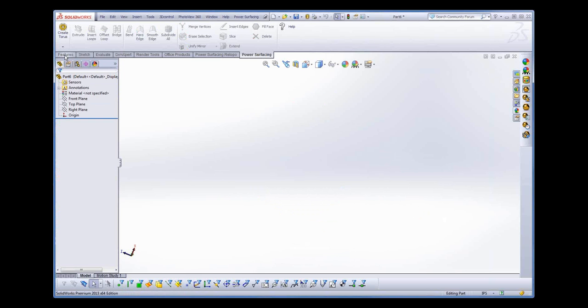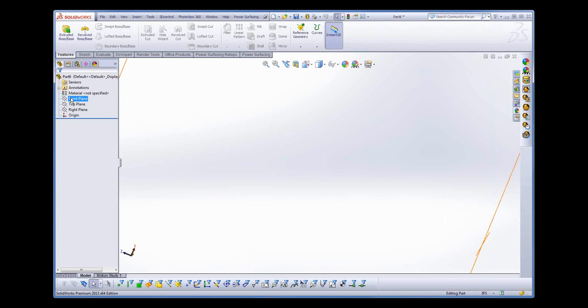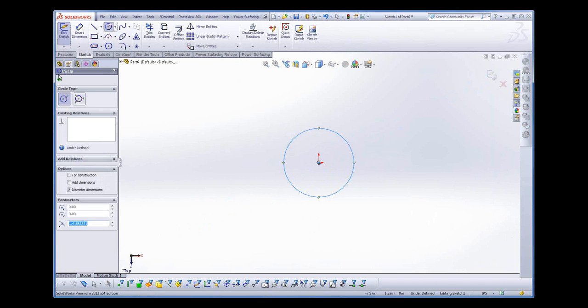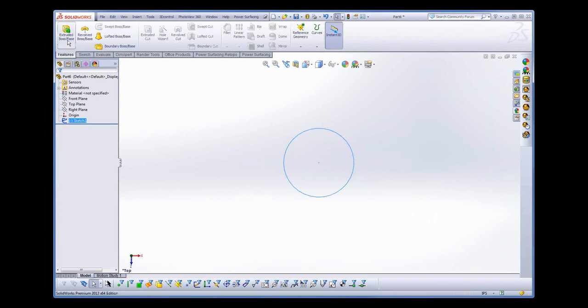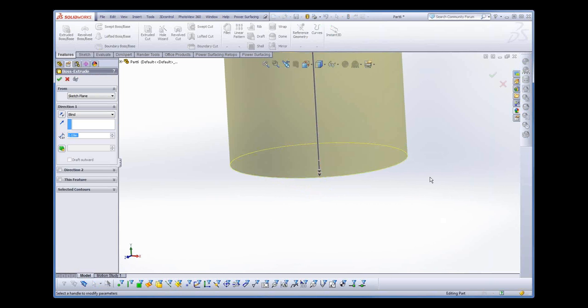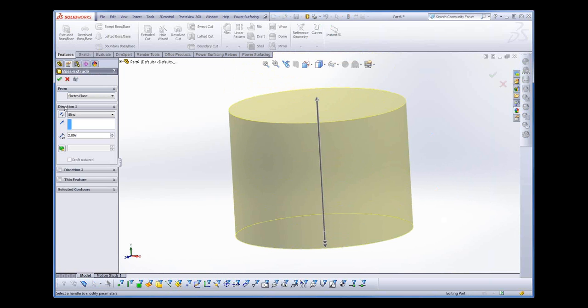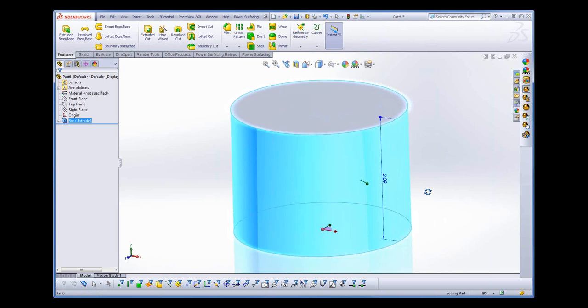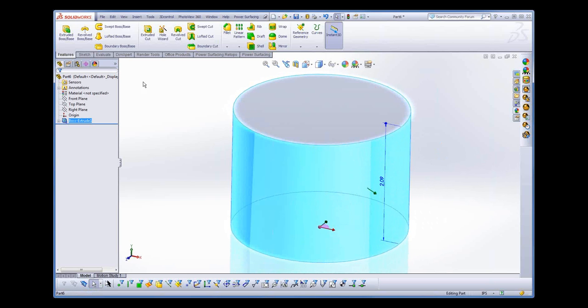Yeah. And so if you bring up the... I was just going to make a quick cylinder. Okay. Yeah, that's fine. So I'm just going to make a simple cylinder here, and we'll go ahead and extrude it. One of the things I didn't show yet was that we can select any SolidWorks surface, and you could create a surface just by extruding the parting line.